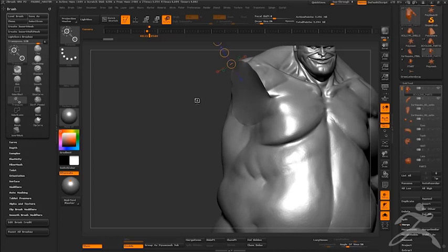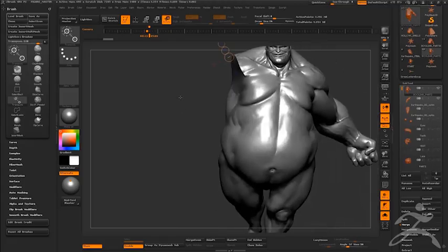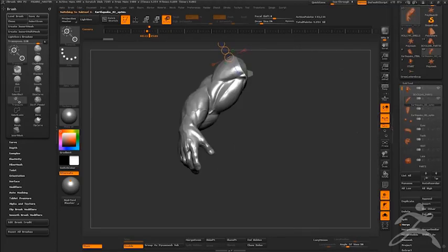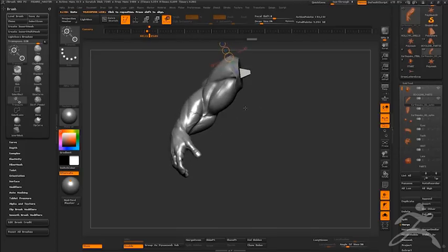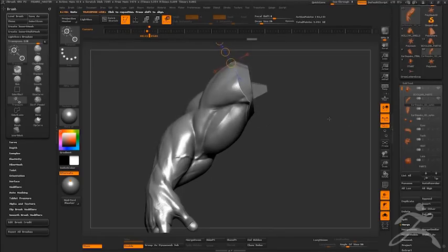So if you make a duplicate of the key that's going to be like a Boolean subtraction, just a little bit bigger, it creates a socket exactly the right shape, but with a little bit of gap to put some glue in. Simply, it's real easy. And then the primary socket that I created is actually going to seat the part where it needs to go, and this is great for super tight gluing.